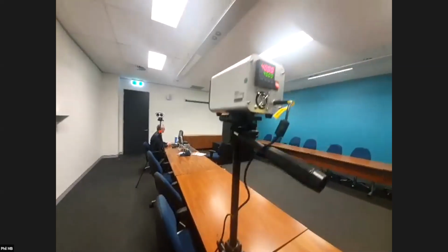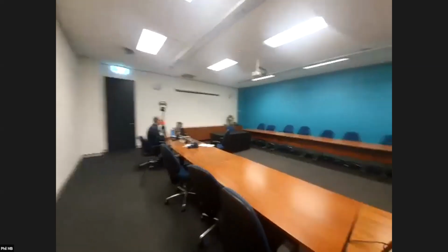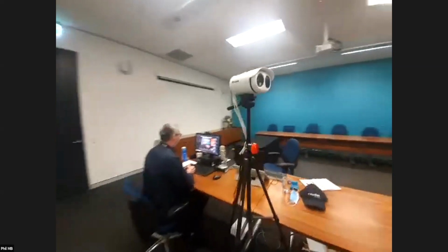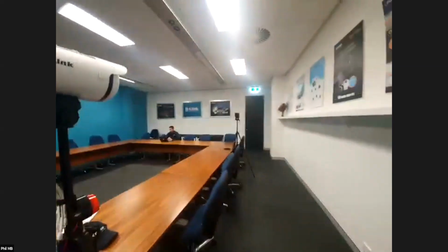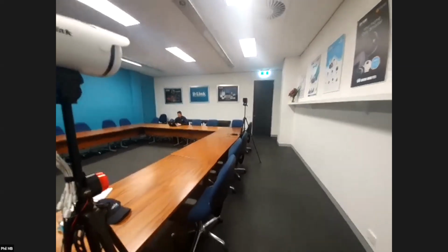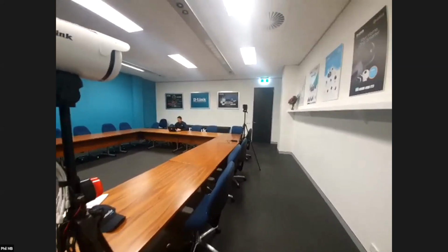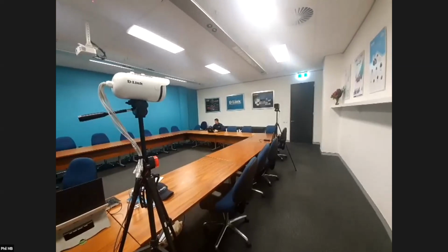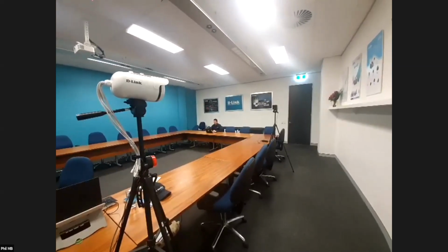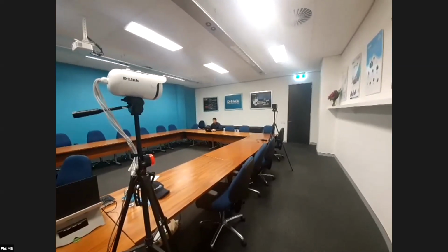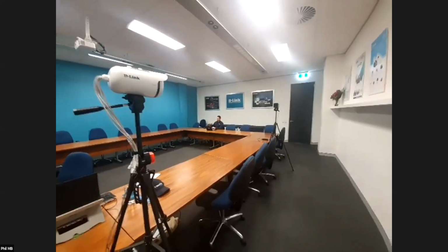The distance between the camera and the temperature reference unit, or the black body, is from 3 to 5 meters. So we've got around 4 meters here. You need to have the black body facing the camera, and it needs to be in the field of view of the camera at all times. It should not be obscured by people. That's why it is better to mount the camera slightly high above the heads or on the side like we have, so when people pass by, they're not obscuring the black body.